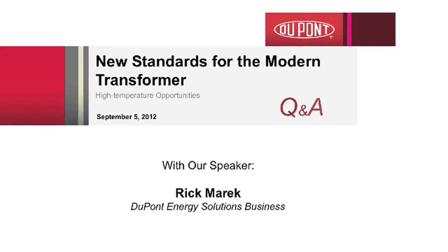So 60 years was given in the example. The assumed life of a standard transformer is 20 years. So you're looking for a 3 times multiplier, and using high temperature could possibly give you that extra length of life without changing the design. You would, of course, have to do an analysis, but the concept is correct. Higher temperature insulation at normal temperature gives you longer life.